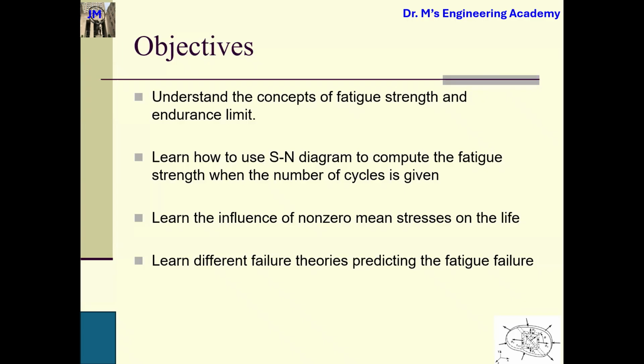Finally it breaks. So you can see why fatigue is very, very dangerous, because fatigue depends upon how many times you have applied the load cycle, back and forth. Even though the stress level is much lower than the yield strength of the material, as the number of cycles increases, fatigue will occur.